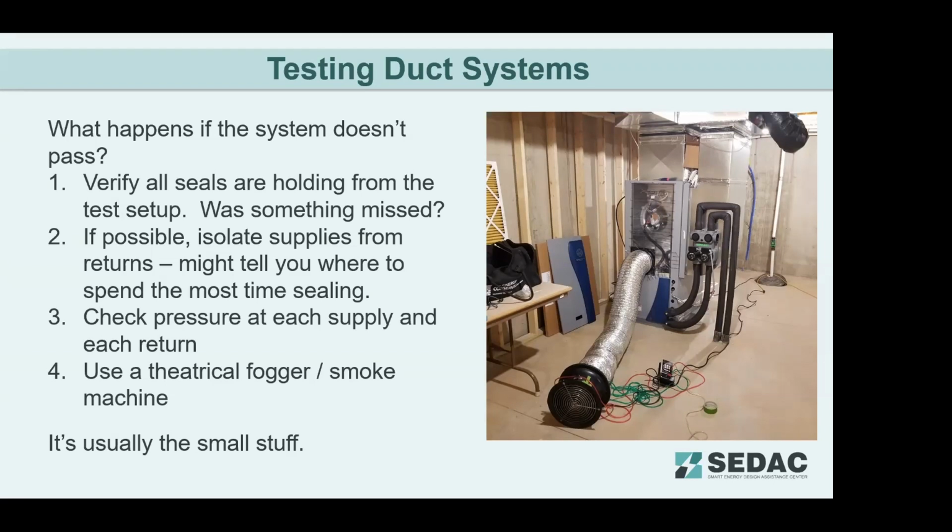You can also check the pressure at each supply and each return. And I don't have a picture here in the slides, but basically if you take a probe, insert it into the tape right in the middle of the boot and measure the pressure inside that, they should be pretty uniform across the system. But if it's not, then hey, then I know this is kind of where I need to spend some time. So basically, you're checking each one individually.